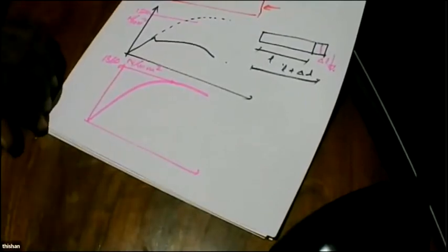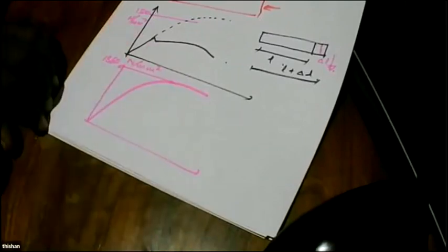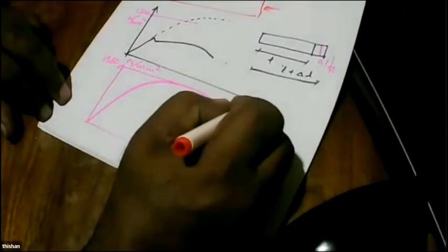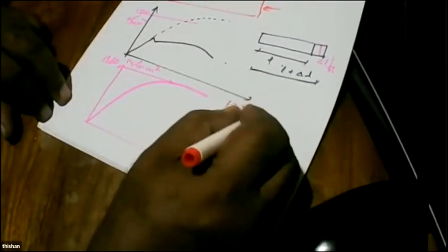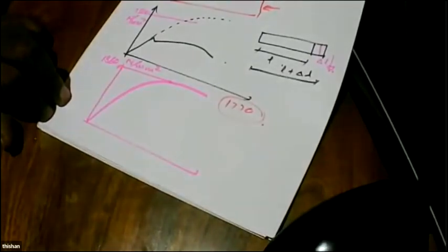These can vary from manufacturer to manufacturer, but generally you can expect something with a maximum around 1,860, and there are some steels at 1,770. There are so many different values, but generally 1,860 characteristic strength or breaking strength steels are available.